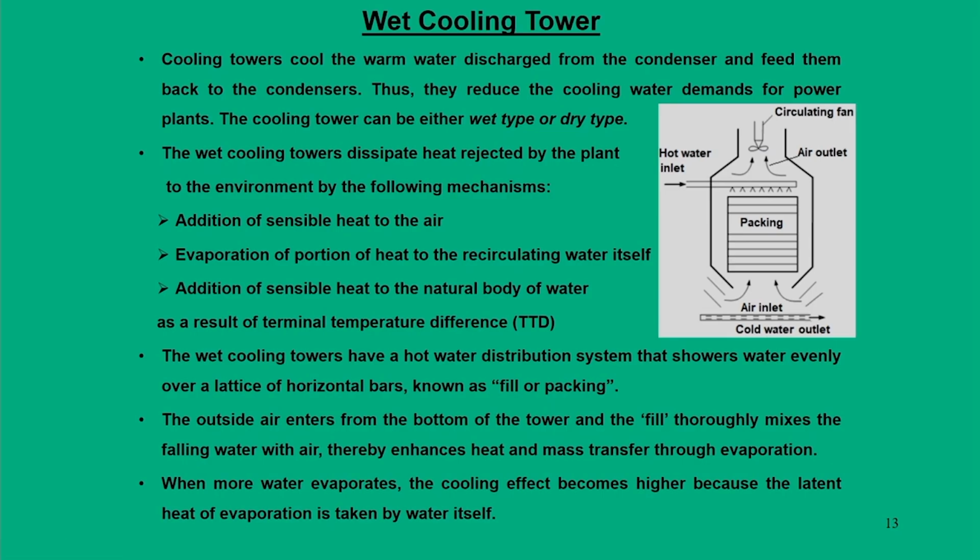So, through this concept, we take advantage of increasing the temperature of air. At the same time, the water vapor concentration in the air is also increased. So air has two temperatures right now: at the starting point it has a dry bulb temperature and a certain wet bulb temperature, but finally, when it goes out, the air is completely saturated. That means both dry bulb and wet bulb temperature of the air become equal. So, through this process we take advantage of air plus water vapor, for the heat rejection process from this hot water unit.